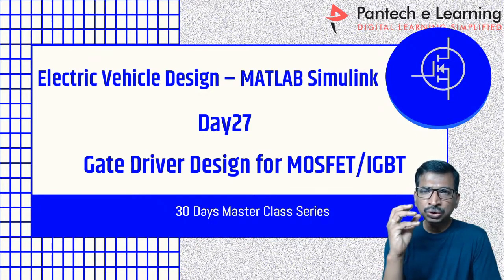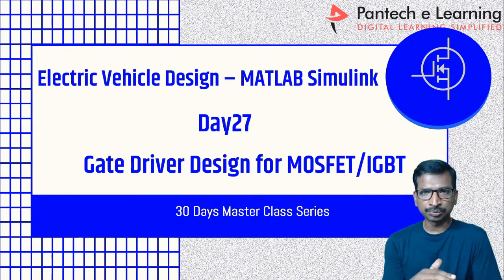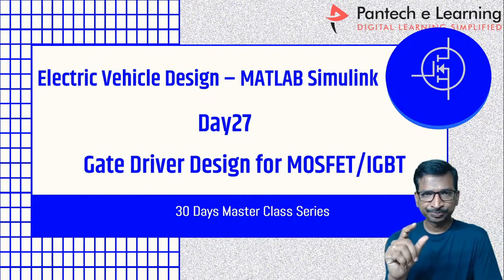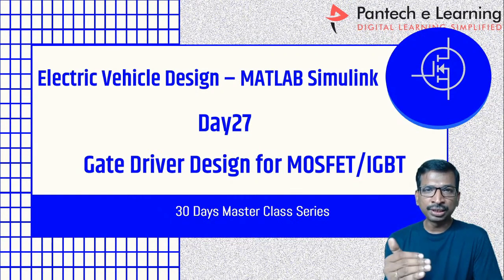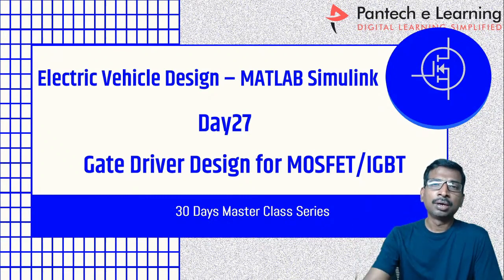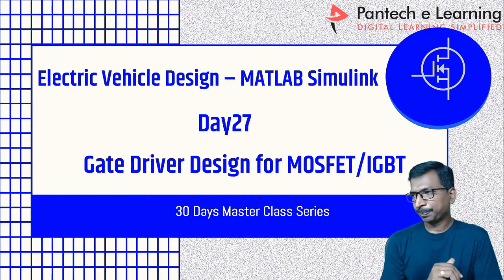That 13 ampere should not flow into the microcontroller, because the microcontroller is a low power circuit. If any fault currents or noise are present on the microcontroller ground, the microcontroller will hang. To avoid that, we have to introduce an isolator between the microcontroller and the power circuit. That is the main objective of the gate driver.